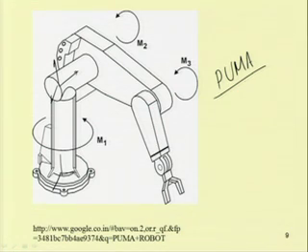Here we have 3 joints, giving yaw, pitch and roll motion in the wrist, and in addition to that we have 3 degrees of freedom here. It rotates about this base, it also rotates about this axis, and it has a revolute joint here also. So, we have 3 major motions about these 3 axes, and yaw, pitch and roll motion about the wrist axis. So, we have 6 degrees of motion, and using this end effector it can take any object from its workspace.